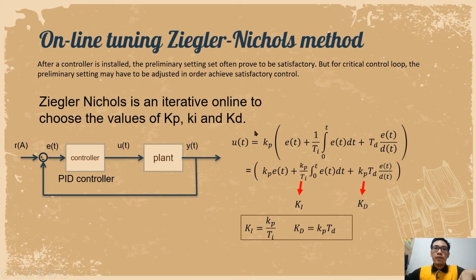Ziegler-Nichols is an iterative online method to choose the values of Kp, Ki, and Kd. Online here means we can do this adjustment directly on the plant without needing a model. So we take a closed loop system consisting of a PID controller. u(t) here is the output function from the controller.